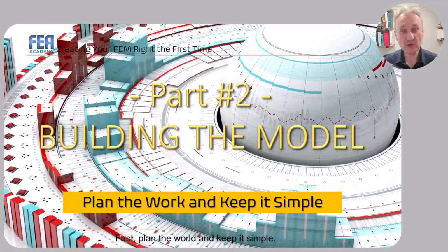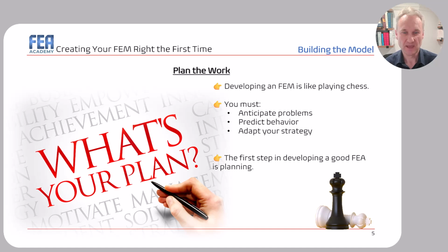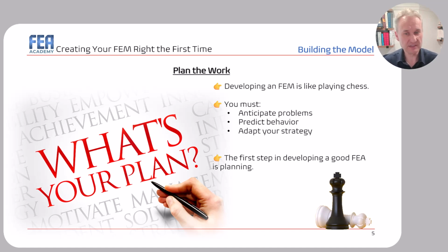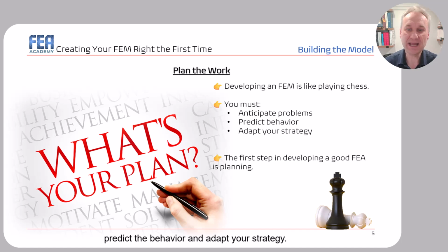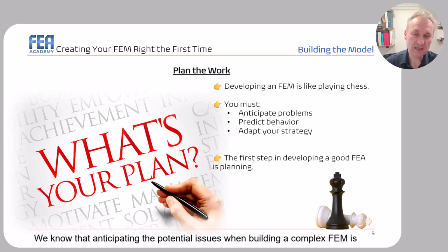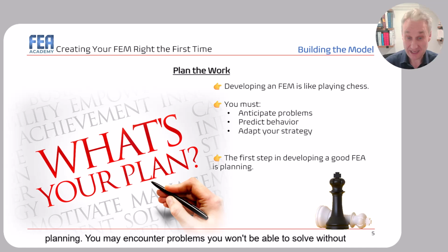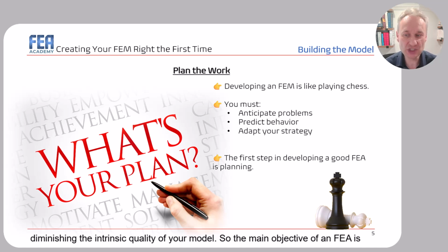First, plan the work and keep it simple. I like to say that developing an FEM is like playing chess. To develop a reliable FEA, you must first anticipate the problems, predict the behavior, and adapt your strategy. We know that anticipating the potential issues when building a complex FEM is not easy. So it is the reason why planning is the key. Without planning, you may encounter problems you won't be able to solve without diminishing the intrinsic quality of your model.